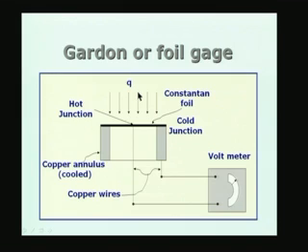So, the constantan foil gathers the heat from the outside here, as is shown here, normal to the constantan foil, and the heat is removed from the periphery by a cooling arrangement, and therefore, I am able to maintain under the steady condition the amount of heat which is absorbed by the plate or received by the plate is exactly compensated by the amount which is removed by the cooling medium at the periphery.